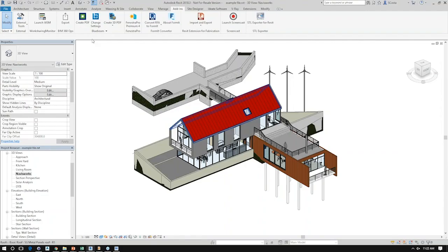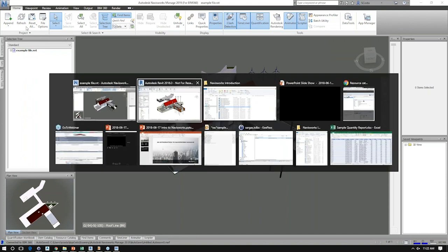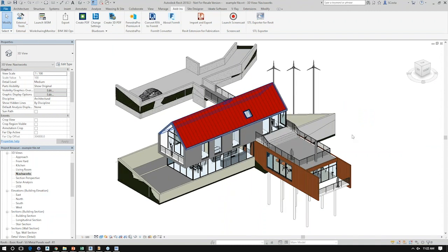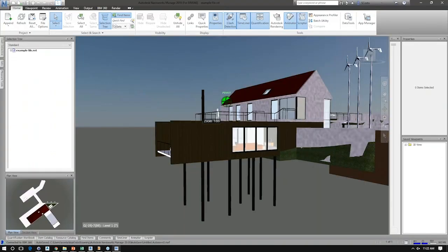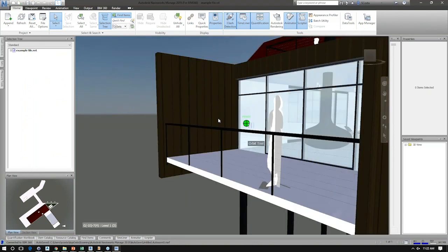Last but not least, I just want to point out, since I am in Revit, and this really has to do later on with more of a clash detective workflow, something called Navisworks Switchback. What Navisworks Switchback allows me to do when toggled, and I've just toggled it on, is to manipulate my Navisworks view. So let's suppose I want to look at these elements here from this perspective, and I need to see that same exact view inside of Revit.